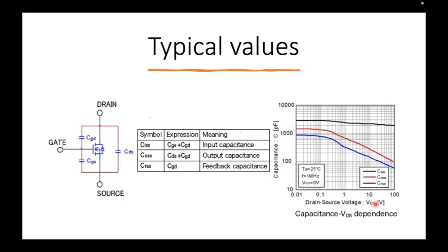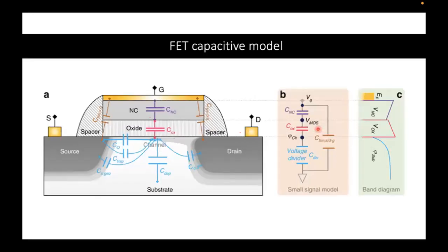But generally, we are considering a picofarad range capacitance, maybe from sub hundreds, tens of picofarad, up to maybe 1 nanofarad. Again, here we can see the 3 capacitances of interest. But maybe this is some sort of a semiconductor solid state topic to investigate such graphs. But now we are considering this from a transistor point of view, from a circuit's point of view. How can this impact us? Actually, this has a significant impact to our design.